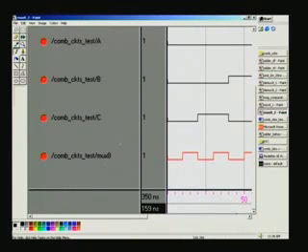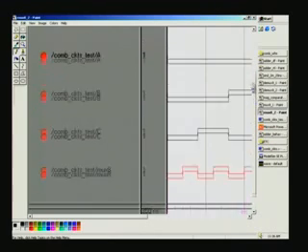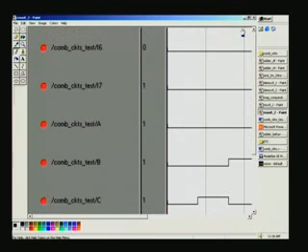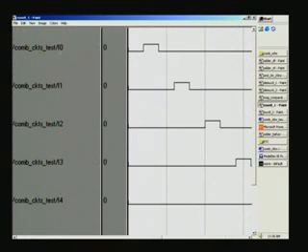This is mux 8 here. Depending upon ABC, if it is the 0 0 0 condition, that is here, you should get the mux 8 output from I0. Let us see whether I0 is pulsed there. You won't get it here because it is in the previous one, that is in this. Say I0 is pulsed here, I1 is pulsed here, it is all subsequent, so you don't have to go back to this file again.